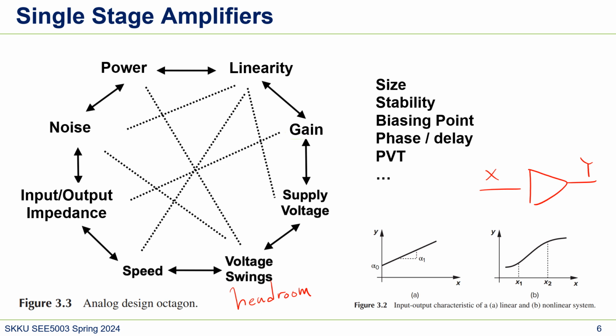And that's the reason why analog circuit design in fine technology is difficult. Let's say 28 nanometer. That's not that advanced, but anyway, 20 nanometer. Actually, I used 28 nanometer. The supply voltage is 1 volt. For a 1 volt supply, it's kind of hard to design the analog circuit because we have to stack a lot of NMOS, and sometimes when we design a circuit, we also stack lots of PMOS too.